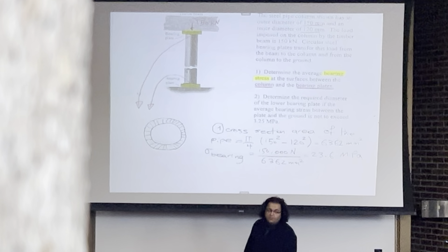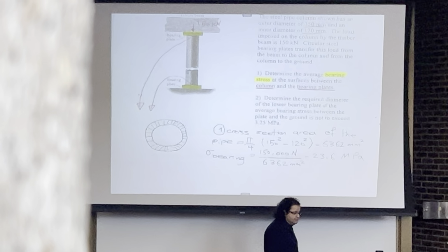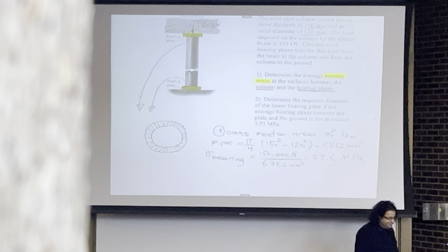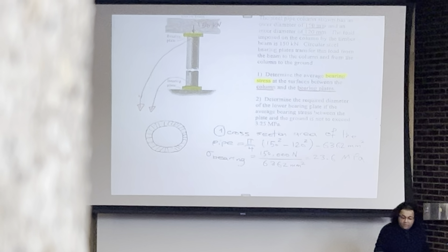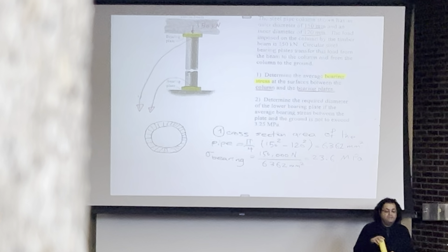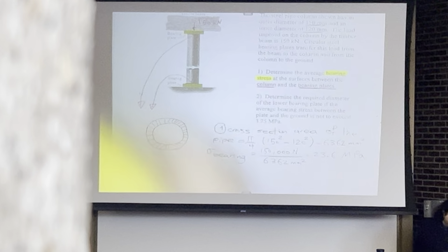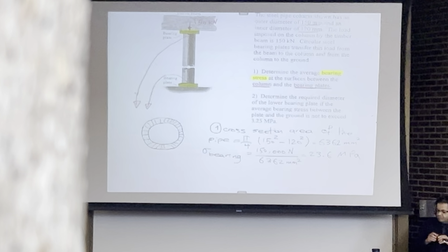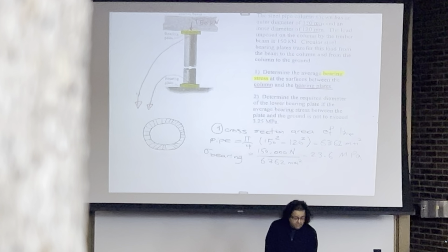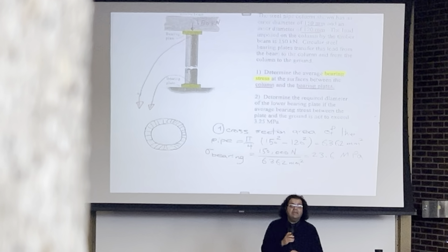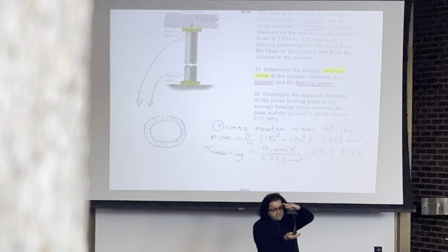This is an important question actually. The height of the column is definitely going to be important, because it defines a parameter that we call the slenderness of the column. That is important for another type of failure that we call buckling of columns. This ruler is a better object to demonstrate. When I apply a compression to a column, without any failure in the material, it can buckle like this.